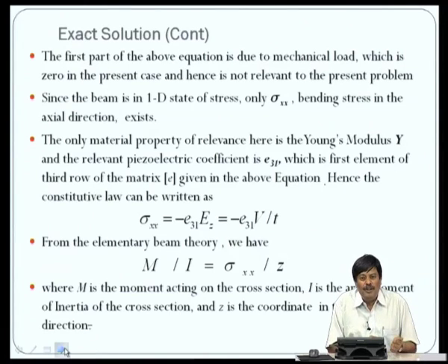We have applied purely electrical loading, which is converted into an equivalent load, that is an equivalent moment, and hence the first part is not relevant to the present problem. Since the beam is in 1D state of stress, only sigma xx acts and the bending stress in the axial direction exists.